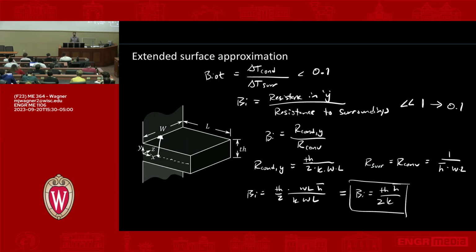This brings up an important point, and that's a very good question. If you're quibbling about factors of 2 in the Biot number, you're doing it wrong, because the point of it is just to prove that a number is bigger than another number. So a factor of 2 shouldn't change your conclusion. But it's a good question. Ultimately, you might differ from the person sitting next to you by a factor of 2 or something. But if you're at this 0.1 threshold, you should be at things like 0.01, 0.001.